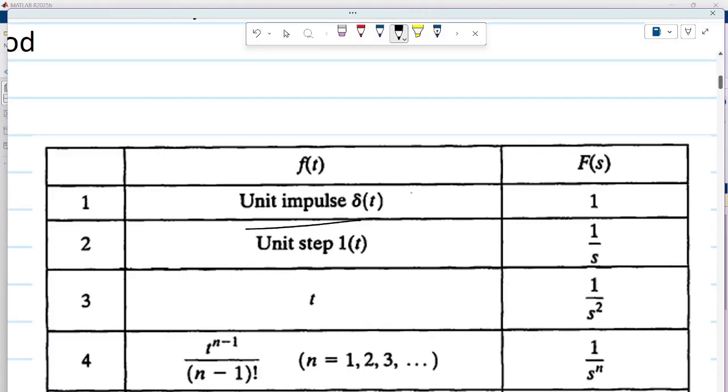that's a unit. So if the force is this one, you just write the Laplace transformation of this force as 1 over s, whatever the step force they mention. The Laplace transformation of that step force would be 1 over s, unless they mention that the step force has magnitude 10, so it will be multiplied by 10, and it will be 10 over s. So this is how you write the Laplace transformation of the step force.